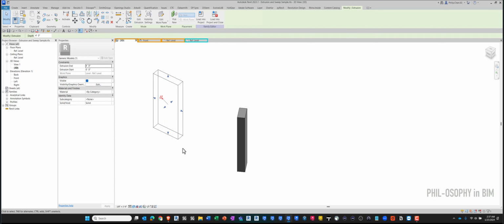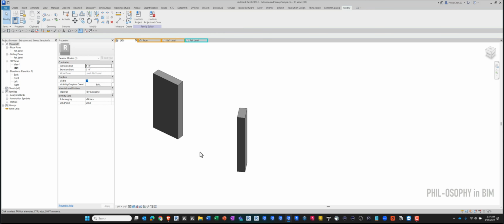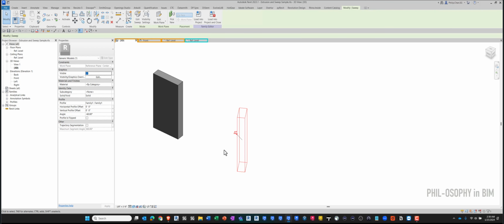If you ever want to rotate an extrusion, yes, there are techniques you can implement, but it's going to require more skill, more knowledge to do it. This one, something that I've been doing for years, is by far the easiest way to create an angle parameter in Family Editor, just by using a profile family in your sweep.